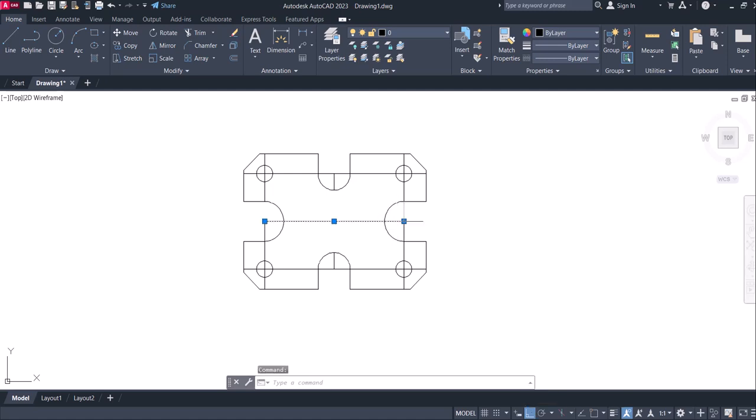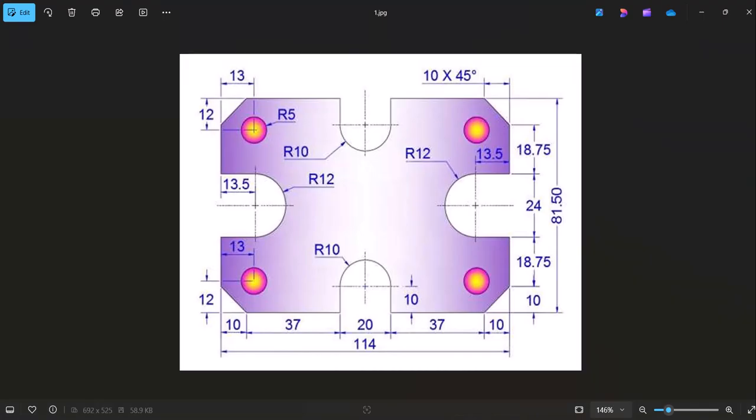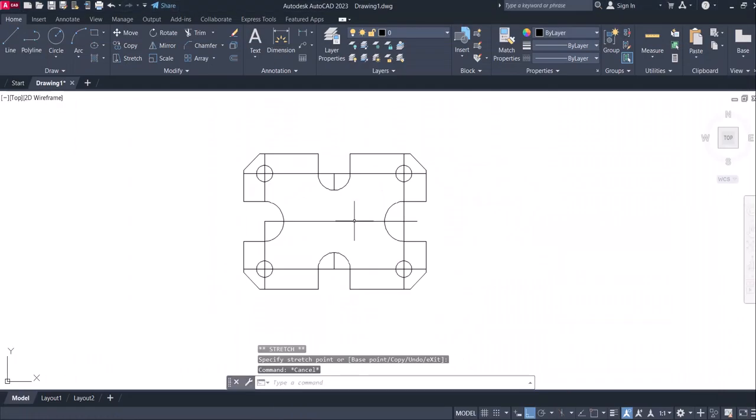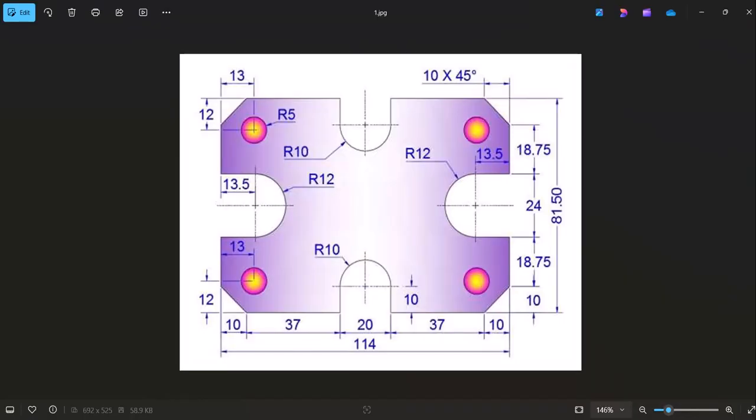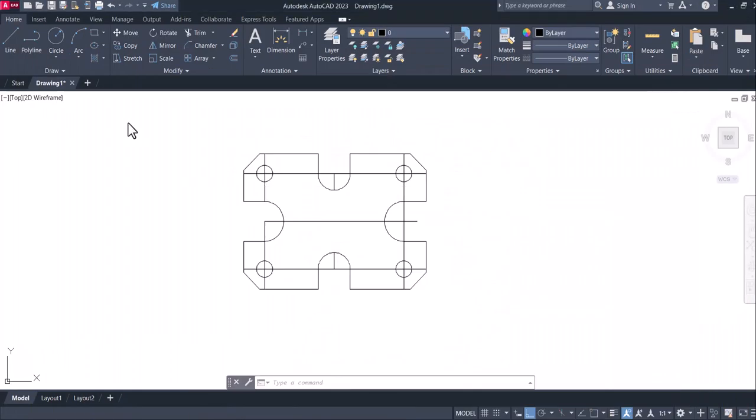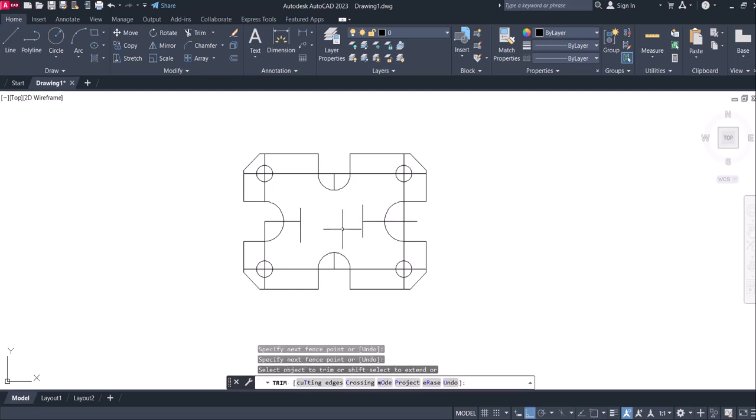So I'll select this line, just select it without pressing any tool, and drag it forward a little bit. I'm just trying to adjust my drawing so that my construction line will be okay. Now this construction line, I want to reduce it. I don't want it to pass through the center. So I'll just draw a line here to intersect it. I'll draw another line to intersect it at this point. Then I'll trim off the middle. Then I will just delete these lines.